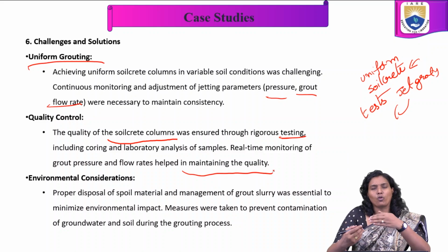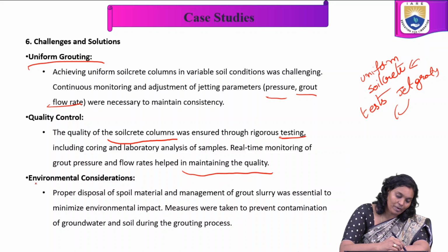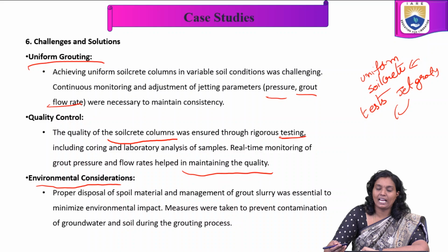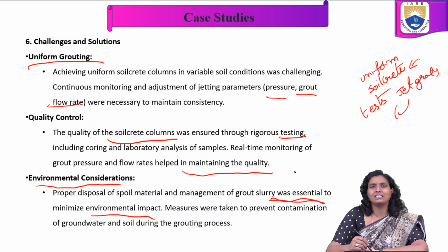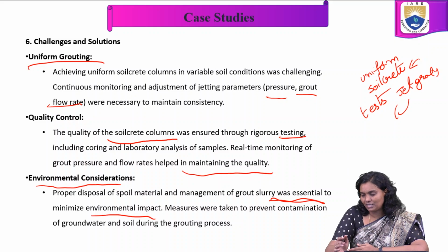Real-time monitoring of grout pressure and flow rates helps in maintaining the quality. Whenever we monitor the grout pressure and flow rates in real time, that helps in maintaining the quality. In these environmental considerations, proper disposal of spoil material and management of grout slurry was essential to minimize the environmental impact. Otherwise, it impacts the environment very badly. If the proper management is not done, it impacts the environment.